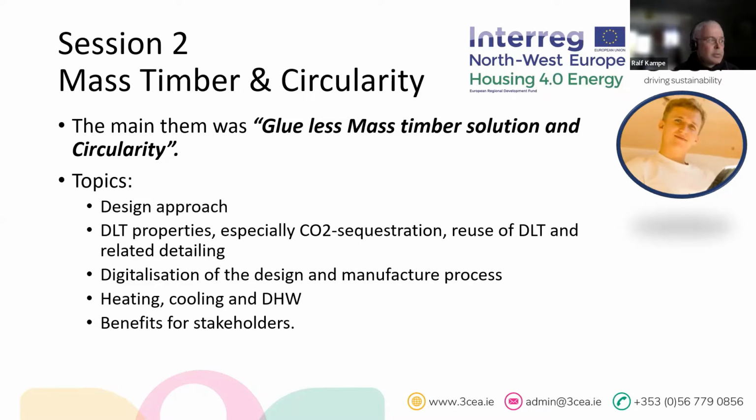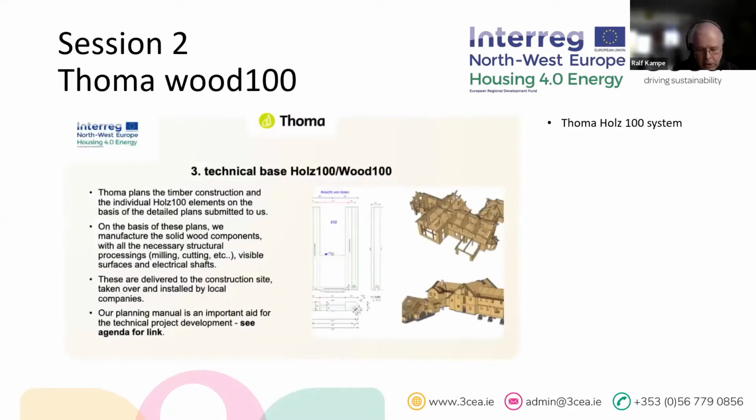And they developed a kind of CLT, but it's glueless. It's called DLT, dowel laminated timber, and it is pressed and connected with hardwood dowels and screws. Really innovative. Florian Thoma and his company have been using that already for 10 to 20 years, and developing a digital factory where they draw and sketch every part before they actually cut it and deliver it on site.